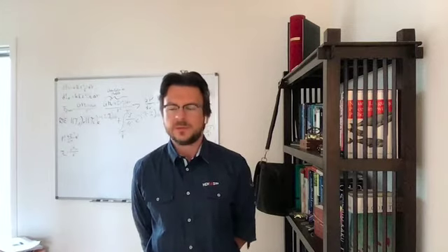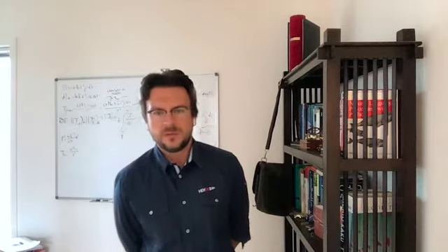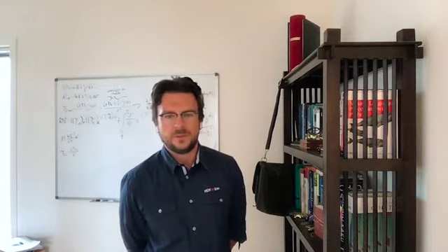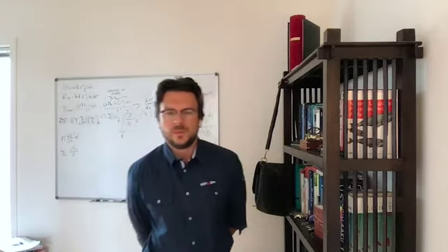A classical gate defines a function f from some input bits, a string of inputs of length n, to some output bits, again a string of zeros and ones of length n. If this function is a bijection, then the circuit is reversible. A bijection means that for each input there is only one definite, unique output. It means you can always conclude back from the output to the input. So if you're given the output of a reversible function, then you can uniquely construct the input.